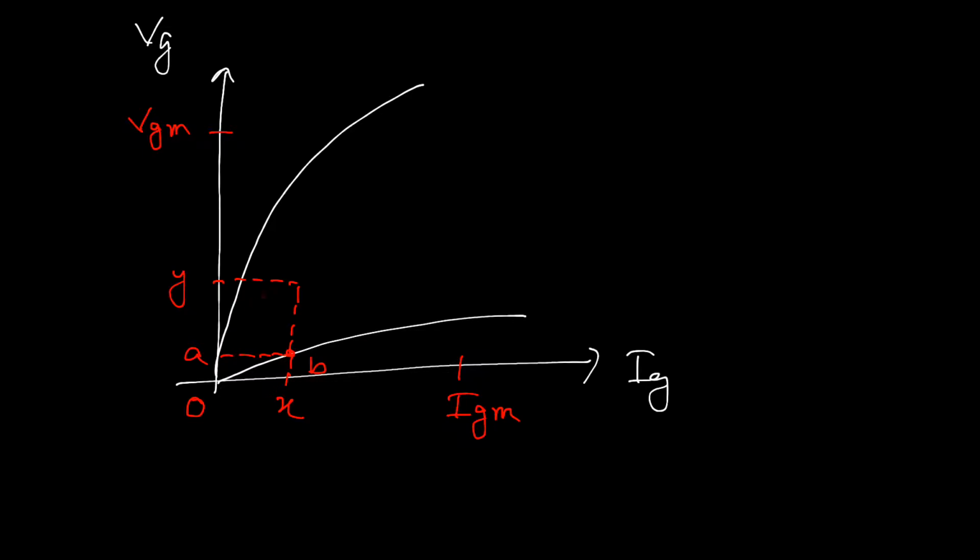That is why this region is called uncertain region, because the turn-on phenomena is completely uncertain. This region is called non-firing region, a non-triggering region, as any point of voltage and current here is not able to turn on the thyristor.